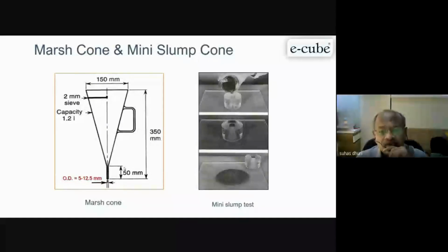So the whole system must be compatible with the particular source of cement for performance in the fresh properties of concrete. Definitely it will also affect the hardened properties of concrete, but majorly it affects the fresh properties. How to determine it? One way is you can use a mini slump cone with only cement paste and check the flow with a particular dosage of admixture.